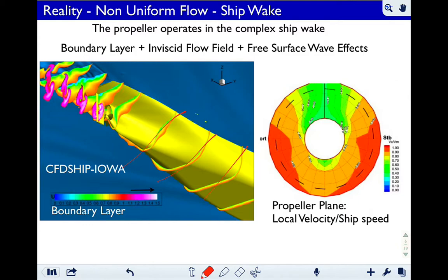And you can see the boundary layer along the hull, and here they're plotting essentially slices from about 0 relative to the free stream speed, so 0 speed, that's the no-slip condition on the hull, up to the speed of the hull. So this is a velocity field non-dimensionalized by the hull speed, or free stream speed.